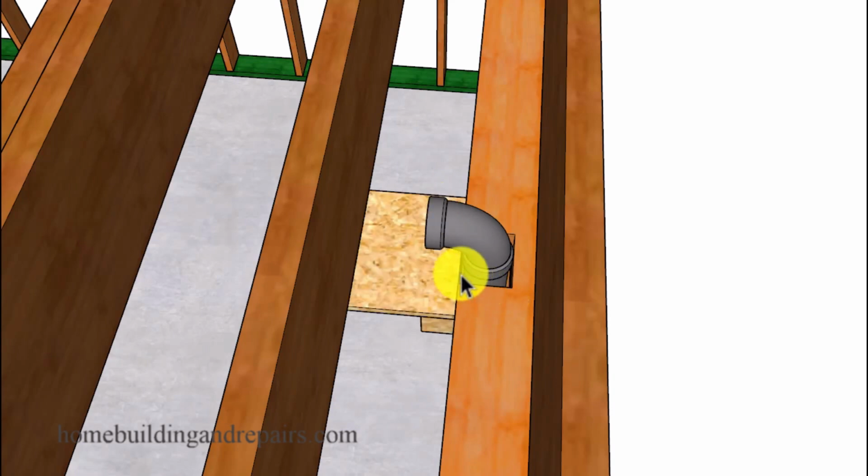Now I'm going to provide you with 2 different methods to do this, and of course the first method might not be necessary, but it's going to give you a better idea of what I'm doing. And we're going to start by attaching a piece of scrap wood to the bottom of the floor joist. This board right here. The width of this board right here should be the same as the measurement between the front of the fitting and the front or face of the wall framing.